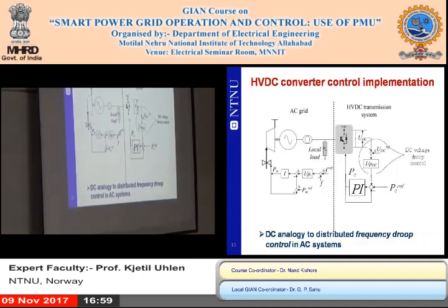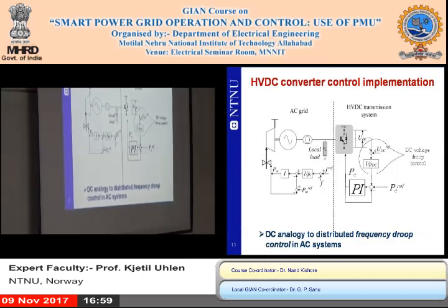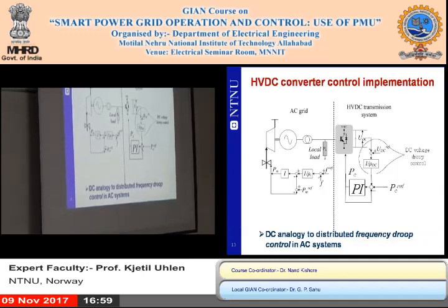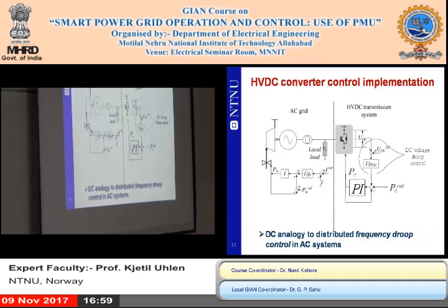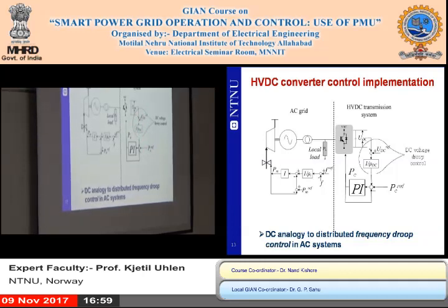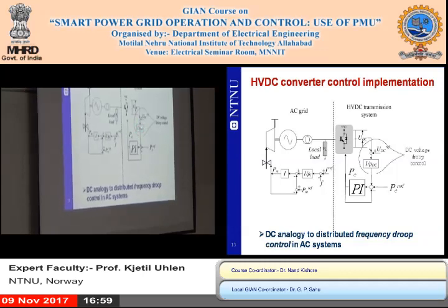So we're talking about voltage source, and as far as I know, almost all the new HVDC links that are being built, at least in Europe, are voltage source nowadays. So with that, you can control power with the vector control, and the outer control loop can have this voltage droop as an additional input. So it's controlling the power reference, but adjusted with the voltage deviation through the droop constant. That's what needs to be done.